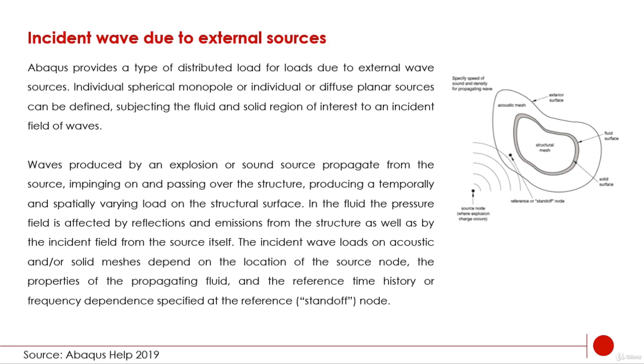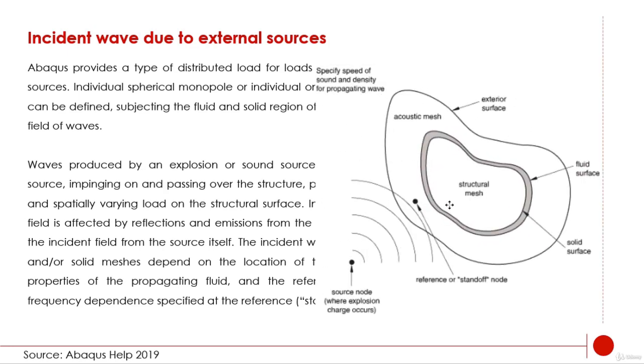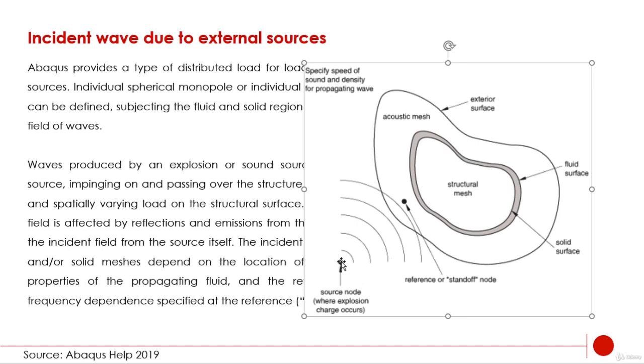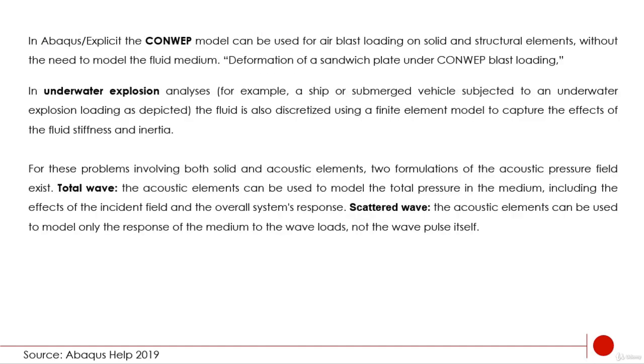So here in this picture, I'm going to make it bigger, you're going to see that this is the source node where we define the explosion, and this is the point that we call the standoff point, and this is the standoff point distance. Here this is going to be an acoustic mesh, and then we have a layer of fluid surface and solid surface, which is the structure mesh in the middle.